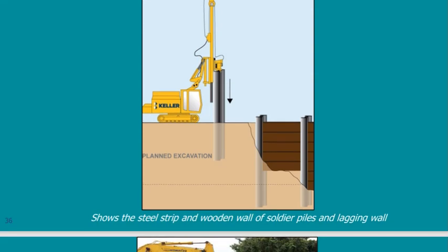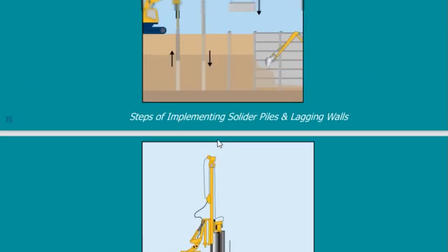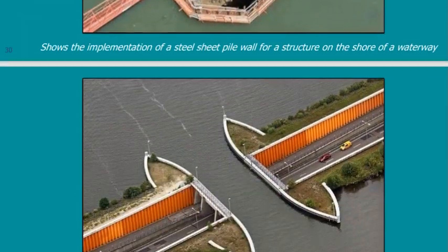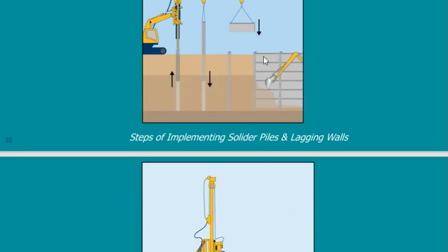And even if the topsoil fails, what's the problem? Suppose that you have an excavation, and while drilling here for the first 50 centimeters, the soil collapsed. Okay, it will collapse once, and I will remove it, but it will collapse for 50 centimeters or 30 or 20. That's all. It will not collapse for the full excavation depth.